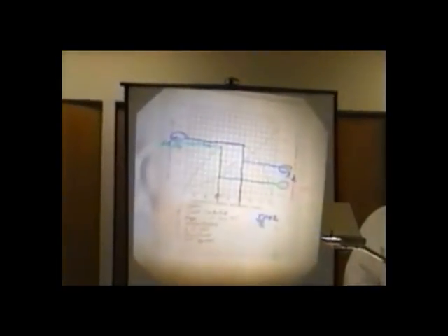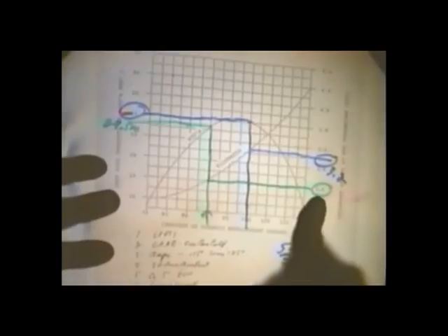So the point is this: I told you the systems are critical, plus or minus 2 ounces. And we just said 10% is 5 ounces undercharge, but look at the electricity he's saving. Is this okay? What happens when the load gets up? The point is, is it okay to do? No! This is how we lose compressors.